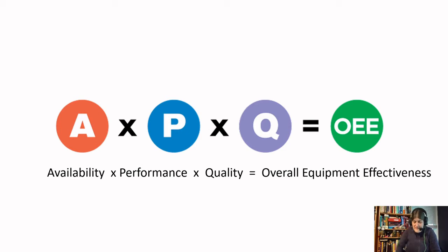But the main thing that I want to say as our take home is that we keep seeing this repeat sequence where we have actual divided by optimal. That's really the pattern that we're going to see for each of these. So actual availability versus the optimal availability, actual performance versus the optimal performance, actual quality versus optimal quality.